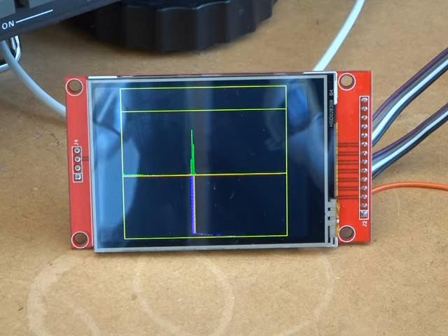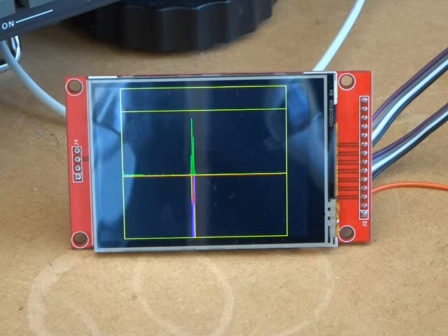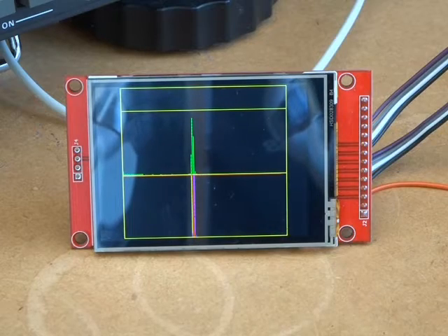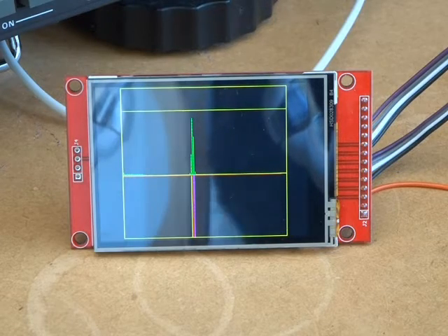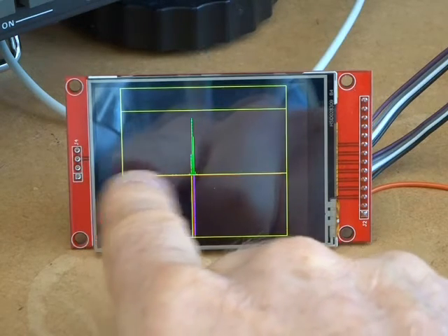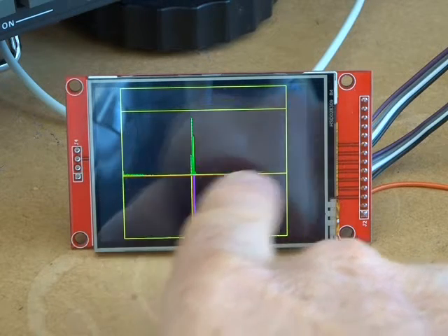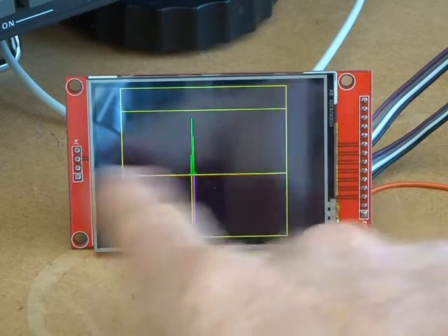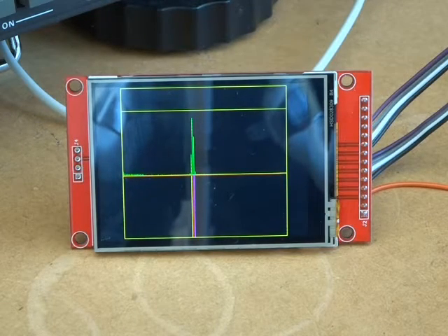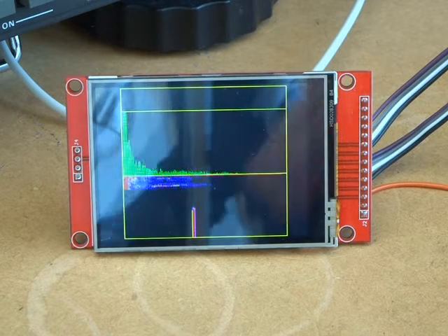As we mentioned in the earlier video, there's going to be that need to transpose our RF coming in down to audio to be detected here. I want to do that on the upstream side of the crystal filter, so I'm not constrained down to that 0 to 2800 kilohertz. I want to be able to try and maximize, like I say, that 20 kilohertz available to us. So that is the desire and the thinking, and I hope we can make that work.